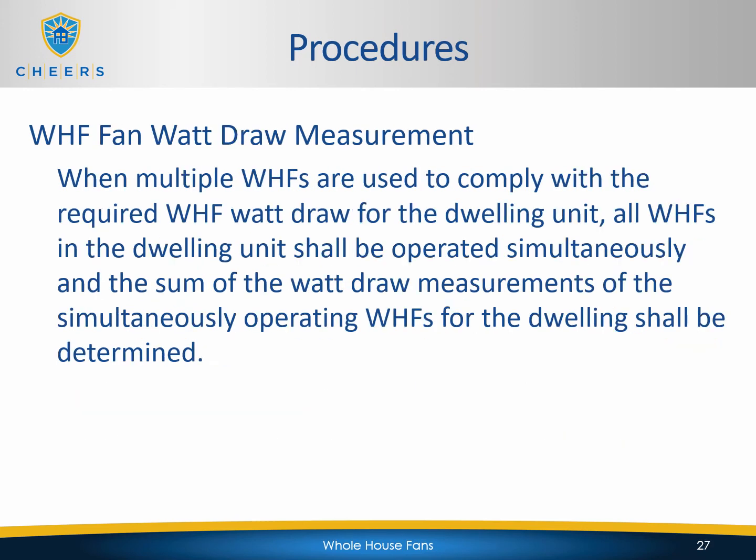So now let's move over to the whole house fan watt draw measurement. So we covered airflow. Now let's look at fan watt draw. These have to be done essentially at the same time under the same conditions. So just like with the airflow, when multiple whole house fans are used to comply with the required whole house fan watt draw for the dwelling unit, all whole house fans in the dwelling unit shall be operated simultaneously, and the sum of the watt draw measurements of the simultaneously operating whole house fans for the dwelling shall be determined. So you're going to measure them all and then add them together if you're measuring them separately.